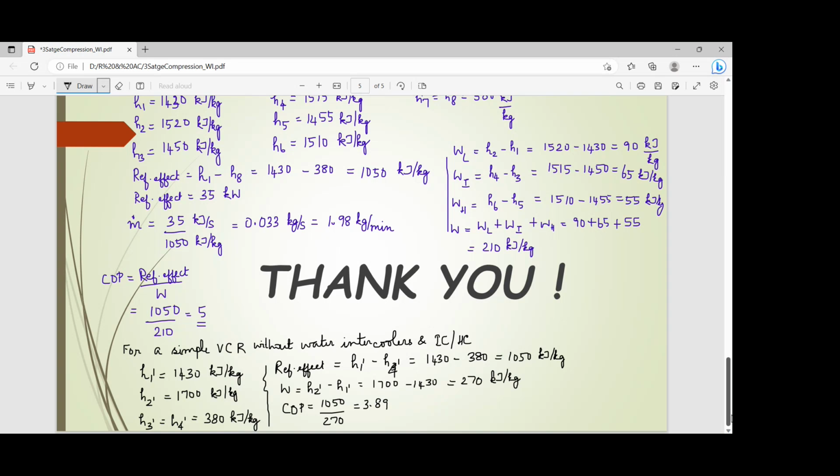So when I use a simple vapor compression refrigeration system with no water intercooling, the COP decreases. So what is the percentage change in COP? That is equal to (5 minus 3.89) divided by 3.89 multiplied by 100. So that would give you the percentage change.